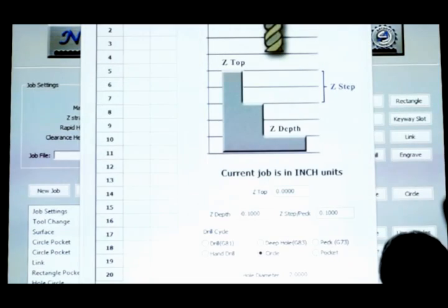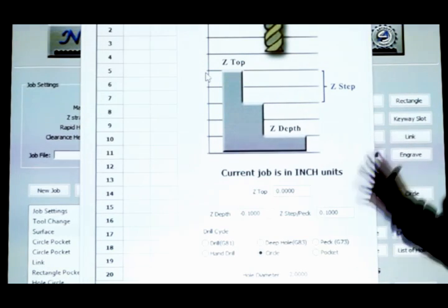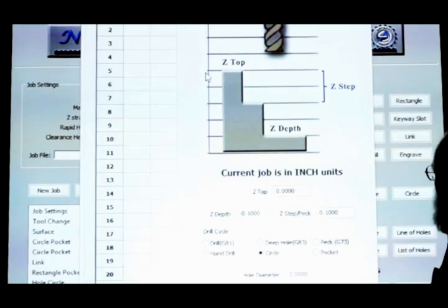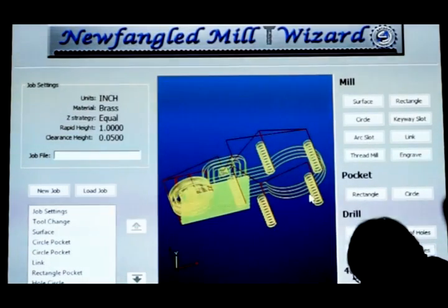The list of holes gives you a table that you can type them into, but, damn, it's down off the bottom of the screen, there's a button that says load from a file, and it takes a standard comma delimited Excel file and fills that table with it automatically. Okay? Well, sorry about that screen resolution.